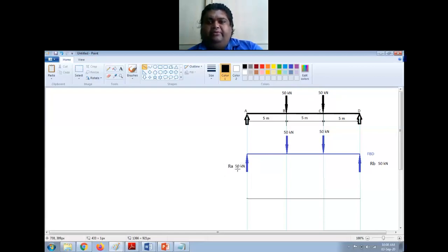Now here I have a force of 50 kilonewton, which is the reaction, in the upward direction. So I will start from here. I will take, let us say, green color. I will draw a straight line which is 50 kilonewton. This is representing 50 kilonewton, whatever scale it can be. There is no need for drawing exactly to scale. If you do it, it is well and good. Approximately, it should be proportionate.